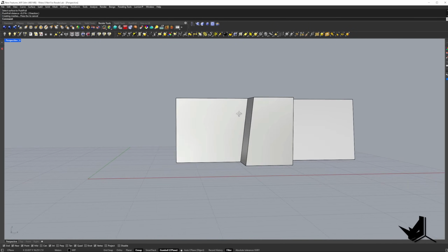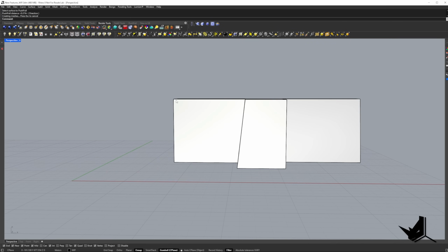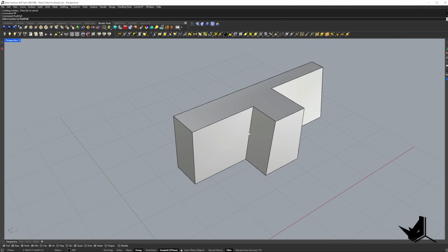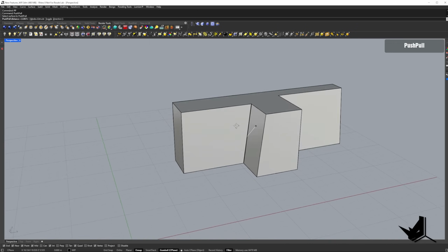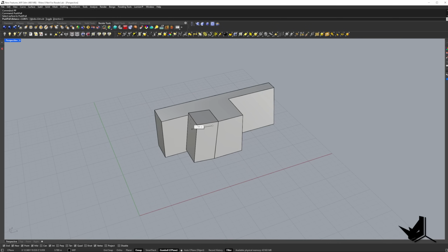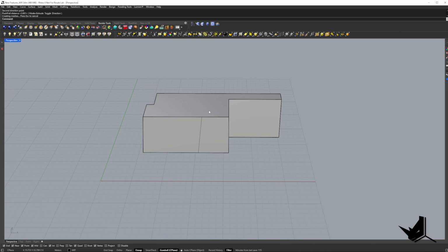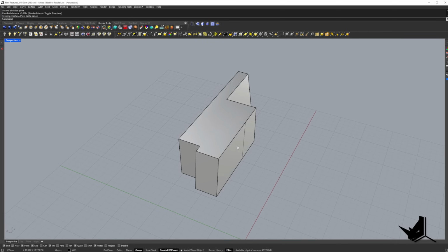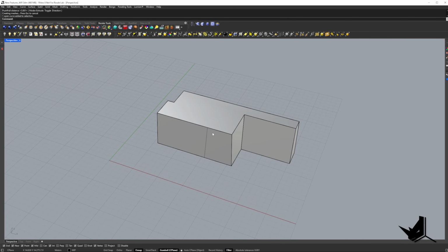For example, here, let's say that you want to connect these faces. You can do push and pull, and if it goes like this, it's going to go straight up. But what we can do is tell it, okay, I want a different direction. So I'm going to click on the direction here, and choose my direction to be this way. And now when I approach here, you'll see that it's going to also merge everything that we have. It's merging, and it's also subtracting the elements. For example, this can be used if you want to make holes for your project.